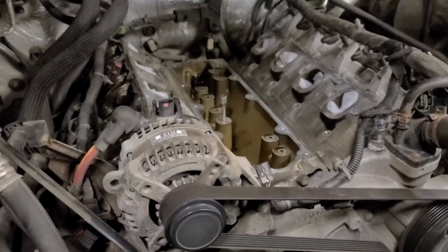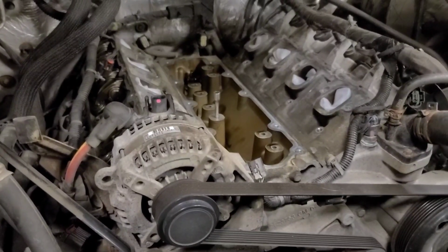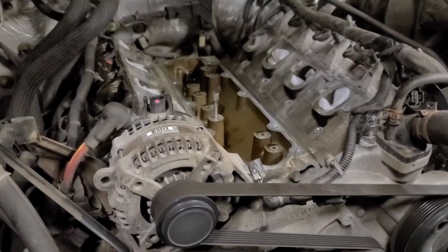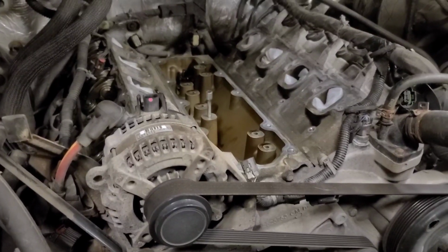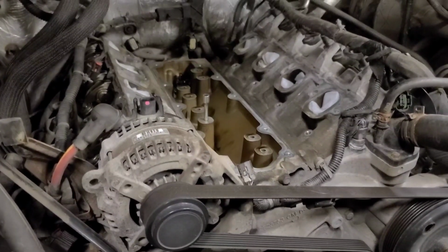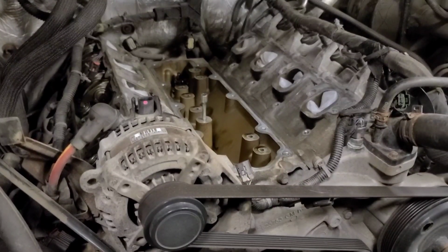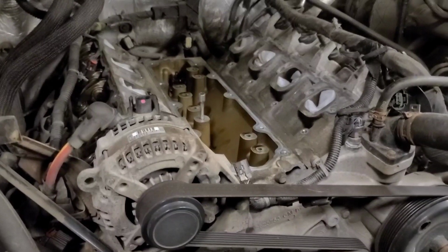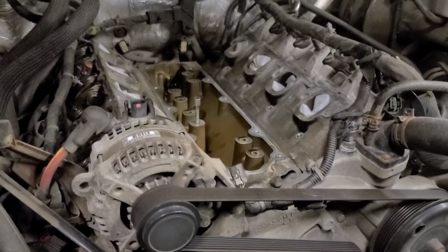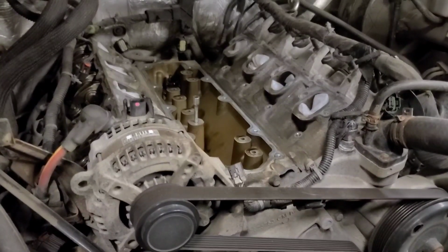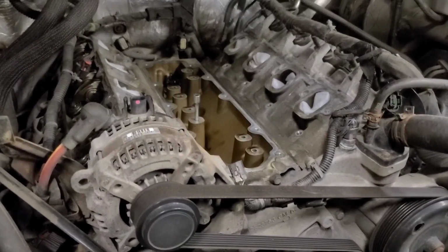So here's the plan. We have sourced a low mileage 2015 engine. It's got 92,000 kilometers, which is just over 50,000 miles on it. Considering this has got over 200,000 and it's got a ton of idle time on it because it was a commercial vehicle, I'm going to replace the engine with this low mileage engine, because to do the lifters you got to pull the heads, at least this one head anyways, and that's fairly time consuming and fairly expensive.